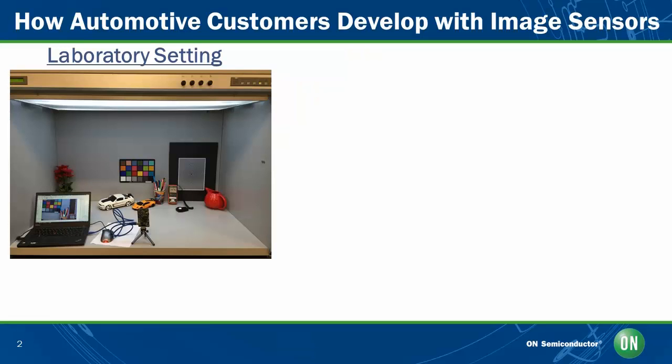So first, I'd like to talk a little bit about how customers in the automotive space develop with our image sensors. In the laboratory setting that you can see here on the left, we have what we call our standard demo system. It's called Demo 3. Every single sensor has a headboard that plugs into this Demo 3, and this Demo 3 plugs into the PC, which has an industry acknowledged best-in-class software tool called DevWare. DevWare allows you to program settings of the sensor, whether it be gains, gain ratios, integration times, various different parameters, frame rate of the sensor in a very simplistic way, and output that to the sensor so you can test with it.